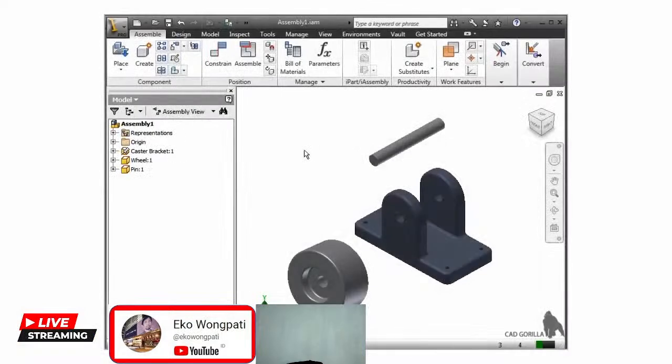Think of assembly constraints as the 3D version of sketch constraints you've already used while designing parts. These are tools that help you create relationships in 3D between components, such as making two components flush with each other, making two cylindrical components concentric, or even tangent. There are lots of different ways to constrain assembly items, but they all essentially work to remove degrees of freedom from components as you add them. Eliminating degrees of freedom allows parts to be attached just like they would in real life.